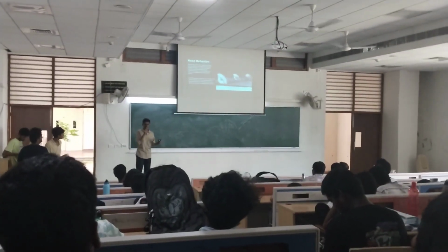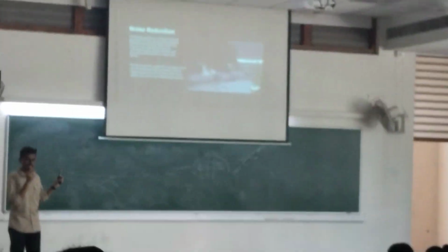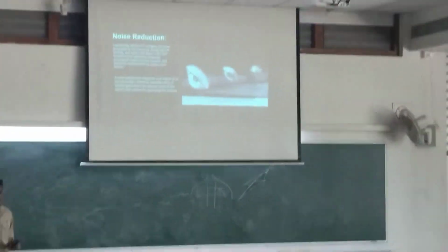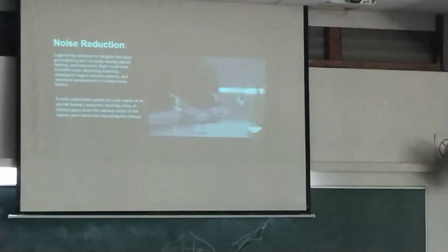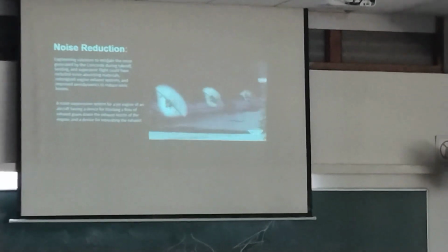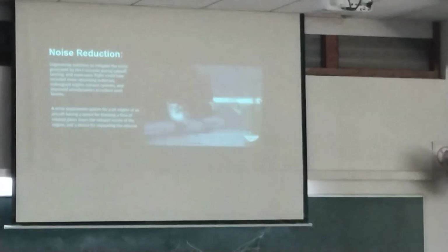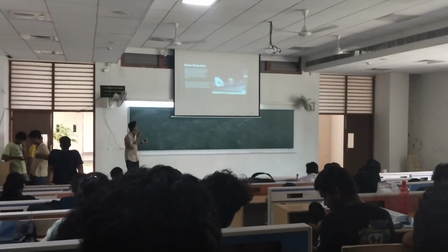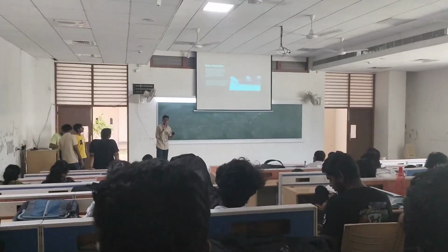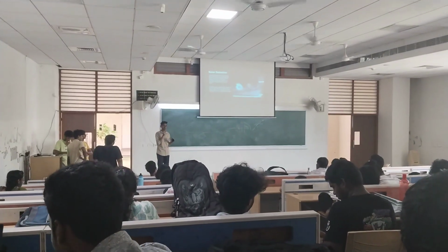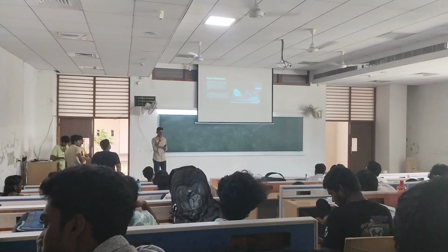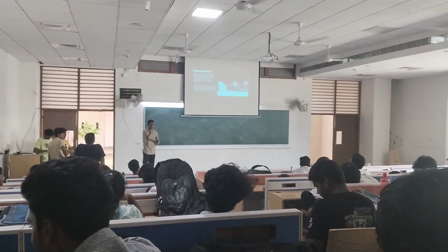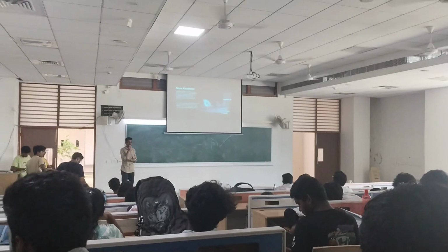And this is the major reason why this plane was banned in 1973. It's because of the sonic boom, which occurs at sonic speeds. These planes break the sound barrier, which makes a heavy noise. So, due to some problems, they banned this. Some noise suppression devices can be used to suppress these sonic booms. So they will control the exhaust gases which go through the exhaust nozzle of the plane.